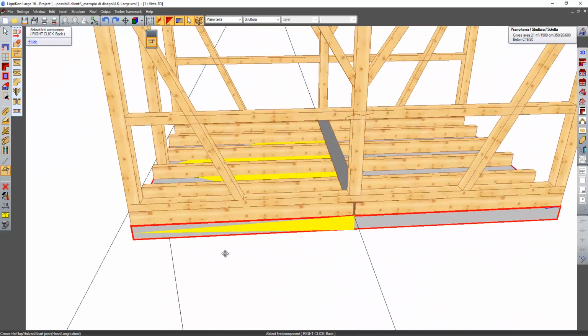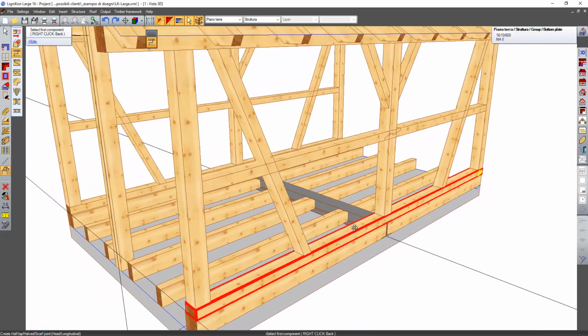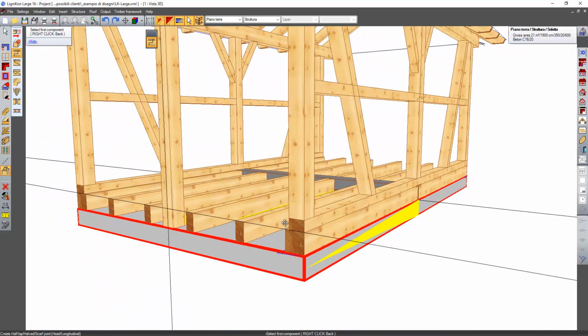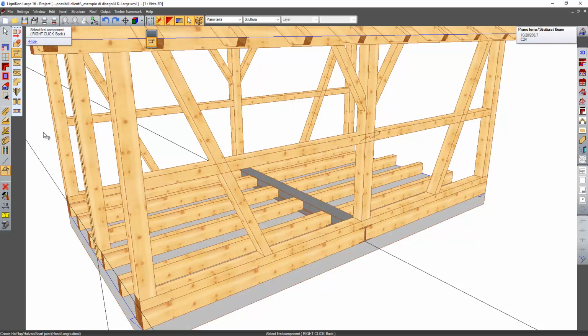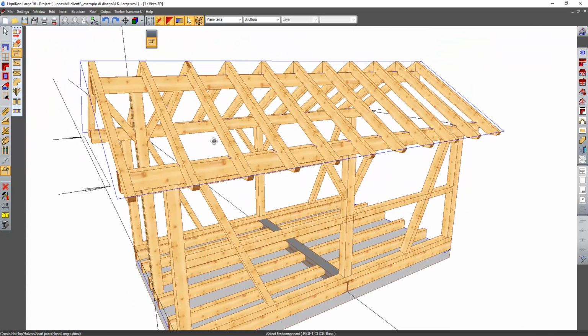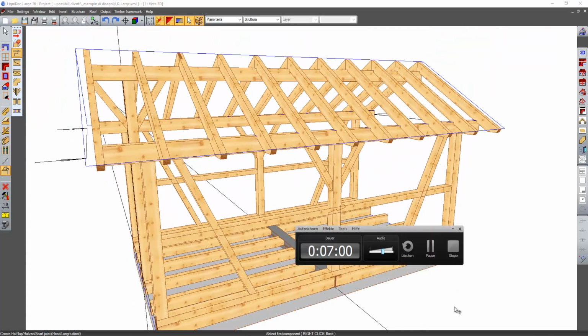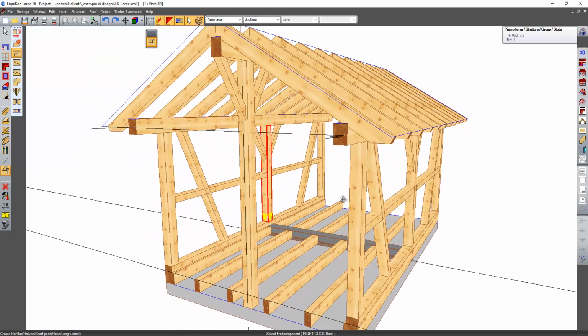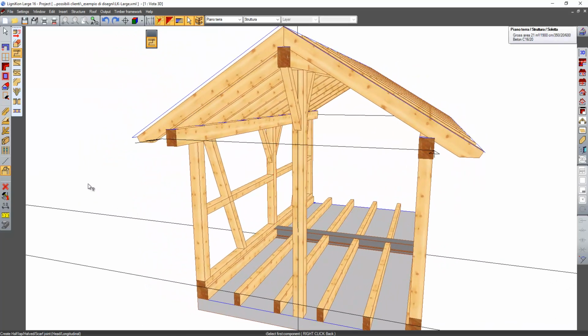For example, here is another element at 90 degrees, but here we do not have a nice situation to show you. You can break. You can have a manual bird's mouth that is also automatic when you make a roof as well, and also a manual bird's mouth in a special situation. So, well, okay, now we are drawing another single element, but manually.